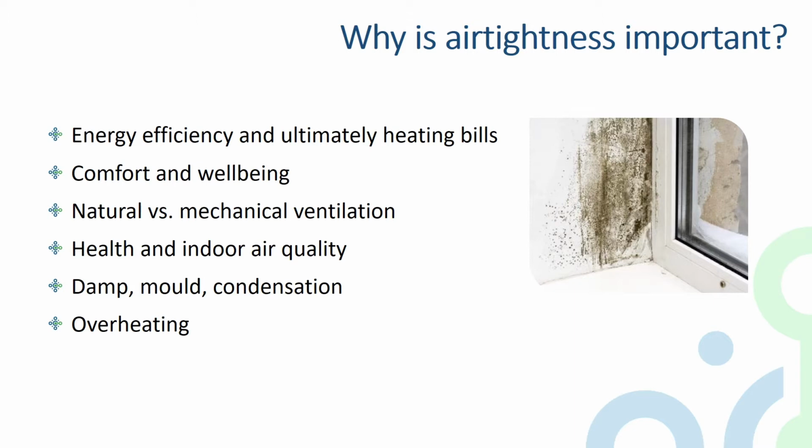It's of course also influencing both the health and indoor air quality of a building. It's both the infiltration and exfiltration of pollutants from inside and outside in a building. So understanding the air permeability is really important in providing healthy, good quality spaces. And the issues often manifest as quite visual problems, so things like damp, mould, condensation, and to some extent it also has a bearing on overheating.